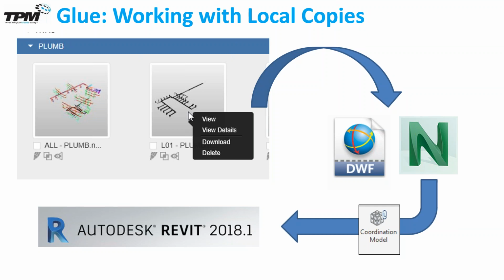It's recommended that if you're using Revit as your management tool, you go ahead and get that plugin so you can work with NWC, because the NWC carries more data in it than the DWF does. Additionally, now in 2018, you can bring that NWC directly into your Revit model. So you can pull down a copy of the latest, greatest version of the mechanical model, plug it into your structural model, and use that as you're working if you don't have access to the source Revit file.